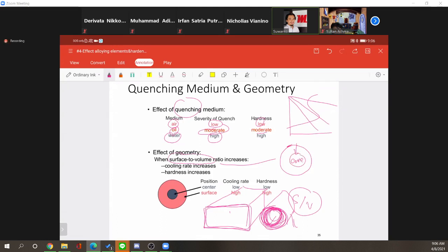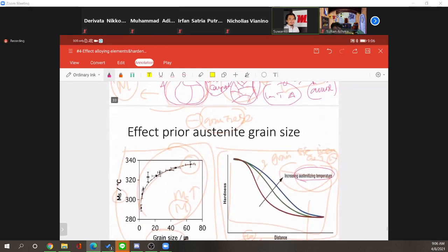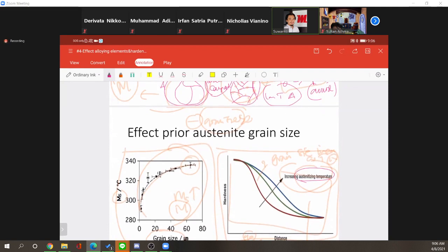There is some practical stuff to consider, but the summary from the slide about the hardenability test is that you should do it with a specific procedure, which is actually standardized. Second, you will have a result, which is a plot of hardness as a function of depth from the edge of the sample.